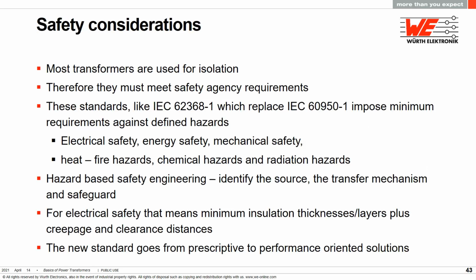Because transformers are used for isolation, they usually have to meet some safety agency standards. The standard today for most electronic equipment is IEC 62368-1, which replaces the IEC 60950-1. It places requirements on the entire system being built for electrical safety, energy safety, mechanical safety, heat and fire hazards, chemical hazards, and radiation hazards.